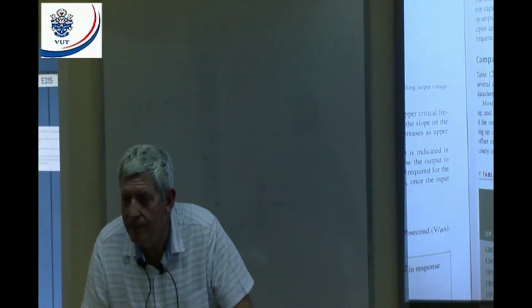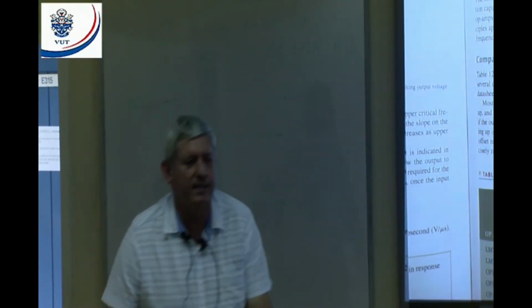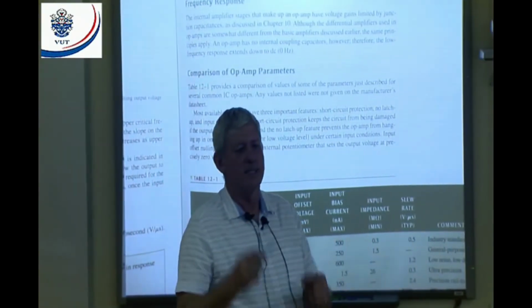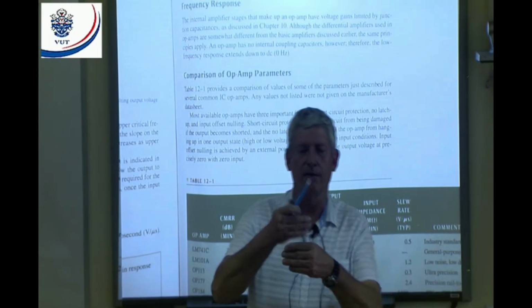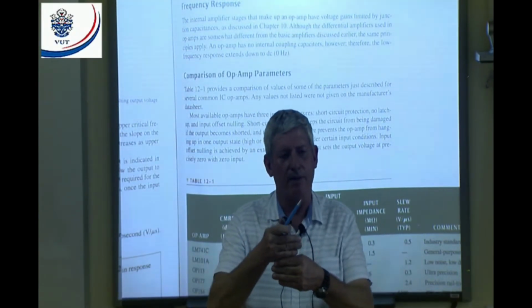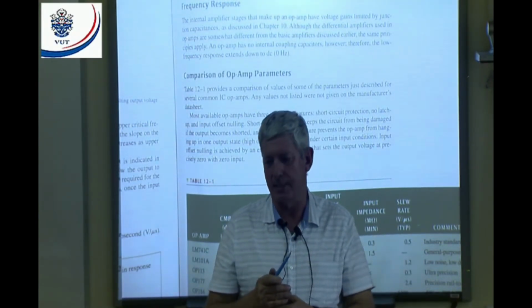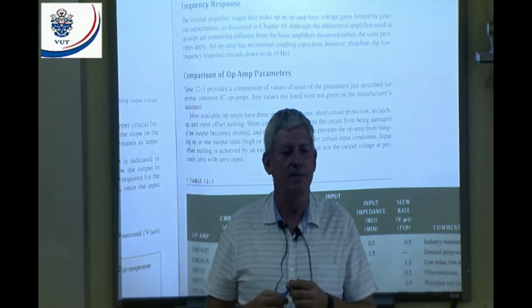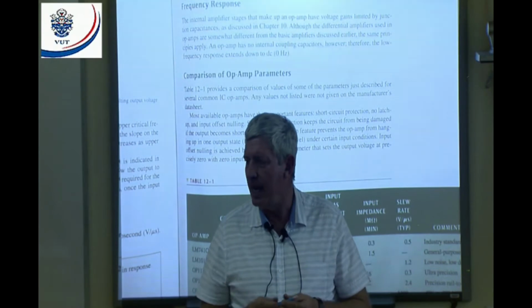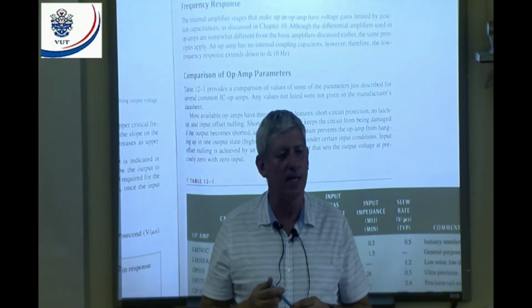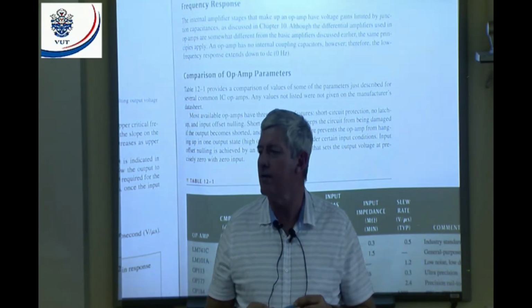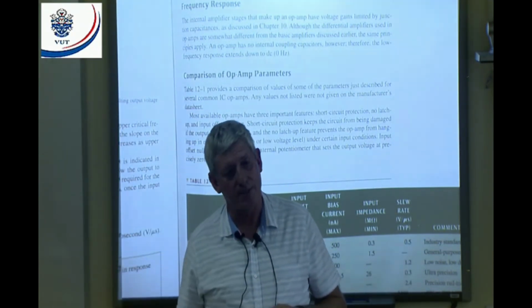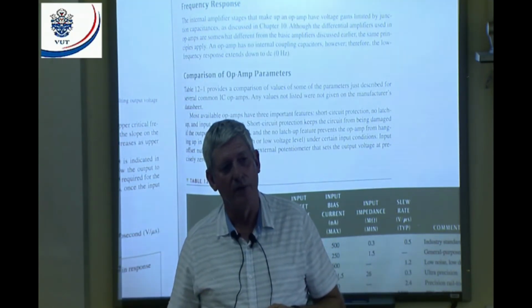Internal? All right. Junction capacitance. Inside a transistor, we have junctions. There's N and P material. It forms a layer, and it will have a small amount of capacitance. But when I go to a high frequency, that capacitive reactance decreases, and it actually creates a short circuit inside the transistor. Then the transistor doesn't function anymore, all right? And that's why it cuts off on the high frequency side. Old news, eh?